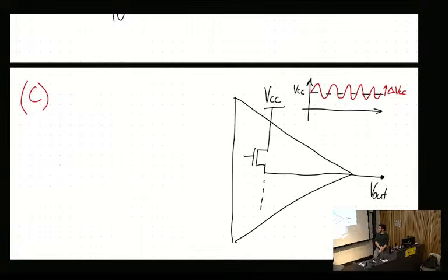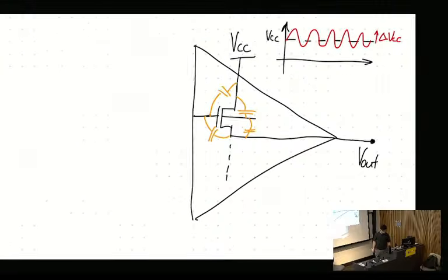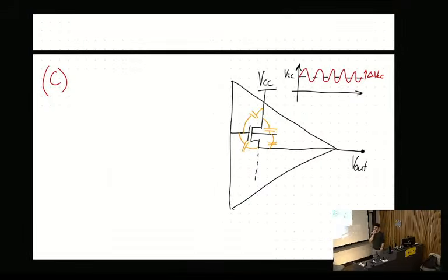Yes. So one of the big ones is the gain of the amplifier itself goes down after the cutoff frequency, right? And so that degrades the actual amplification ability of the amplifier to amplify the normal input signal. Another one which is maybe not so obvious, but just as important, is that there is parasitic capacitance all along this amplifier. And an actual MOSFET has a bulk there, and so then it looks like that. So I've drawn that bulk. That's not content in this course, but just to show where the parasitic capacitances are.